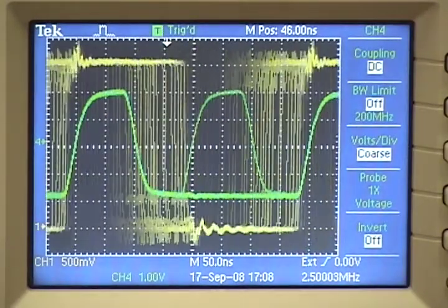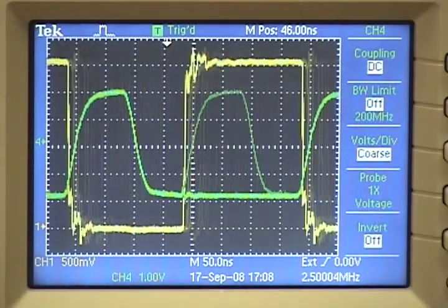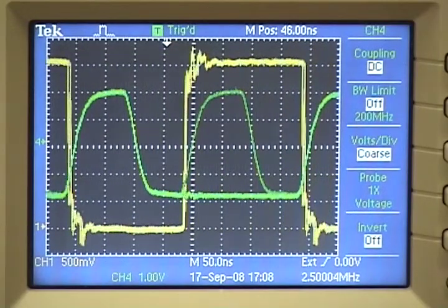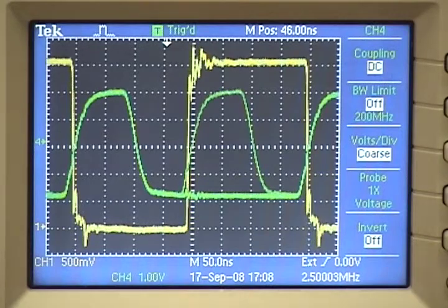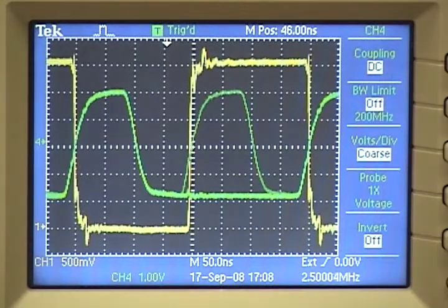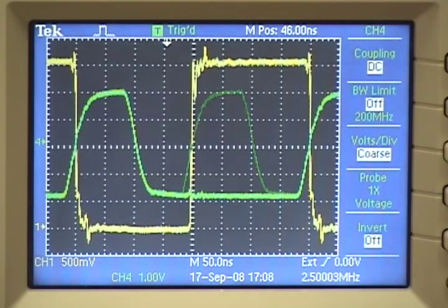As you can see, we have real-time control over the timing relationship between the rising edge of the sampling clock and the video pixel period. We can place the sampling point anywhere within the pixel period, with a resolution as fine as 100 picoseconds.